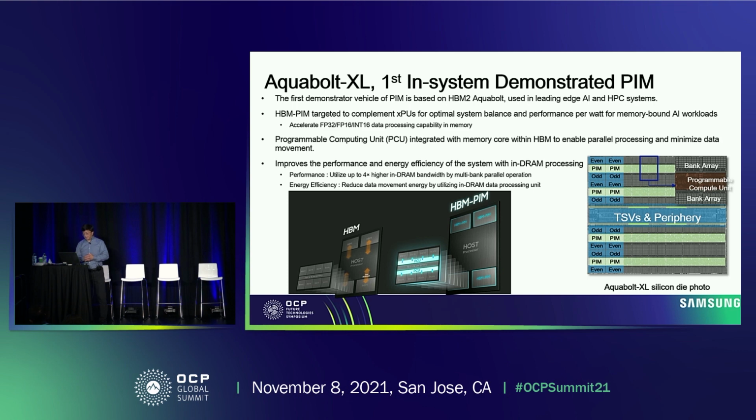Note that we're not trying to replace or displace CPUs or GPUs or TPUs, right? The transistors in the bleeding-edge logic processes are still way faster than the transistors in the DRAM process, perhaps by an order of magnitude. So it doesn't make sense to start moving a lot of compute-bound tasks into the processing-in-memory device. At that point it becomes a decelerator rather than an accelerator.